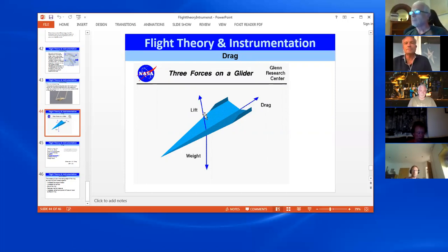Now, again, this is something that people sometimes struggle with: they're in equilibrium. Lift and drag balance your weight, or the weight generates enough drag that it compensates the lift, whichever. You'll notice when you fly that you're not accelerating up or accelerating down. Given everything else is equal, you're at a constant speed. If you're at a constant speed, there is no acceleration. Because there's no acceleration, you must be in equilibrium. It's just basic physics.